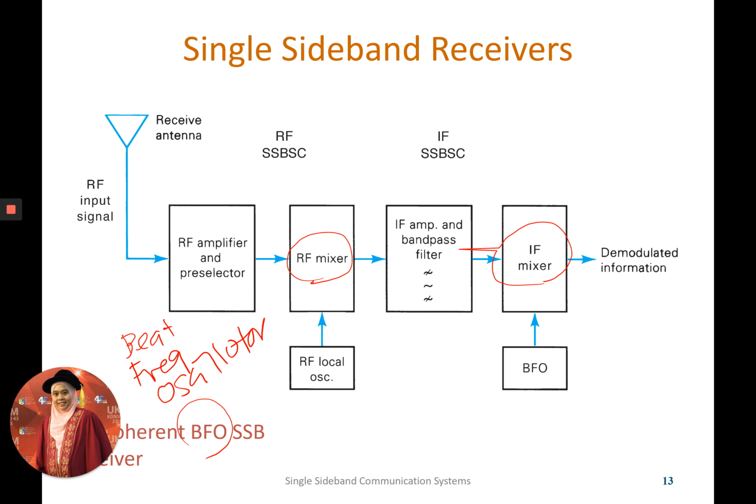Okay, so for this one we have what we call the beat frequency oscillator here, and we always want to tune the frequency of the BFO to be equal to the IF carrier frequency. Okay. This is for the non-coherent.